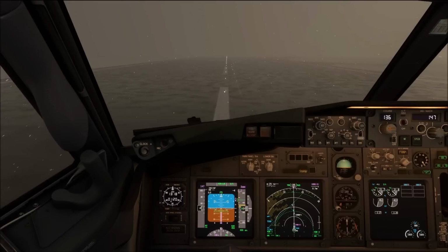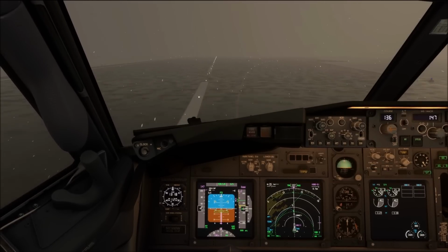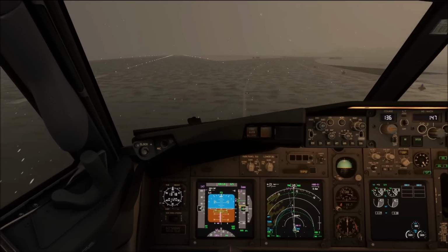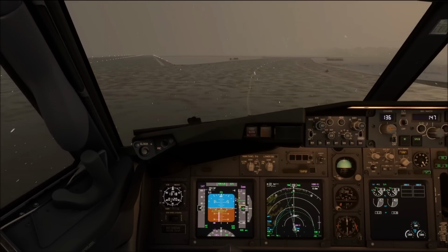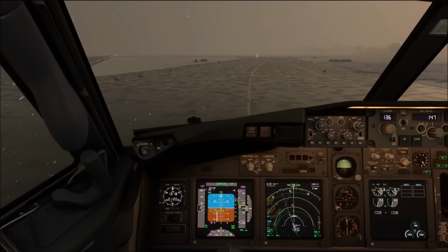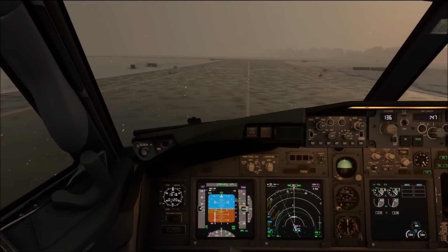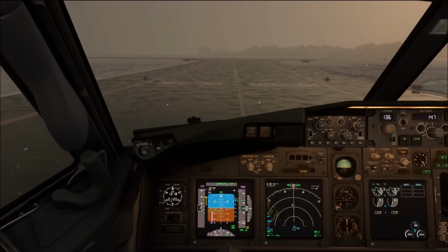Talking about getting towards the end of the runway, there have been a couple of runway excursions already that related to a specific rule, and here it is. Typically the first two thirds of the runway may be well cleared from any contaminants or snow. But the last third of the runway is rarely used because aircraft will usually be airborne before that, or will usually vacate runways earlier than that last third.